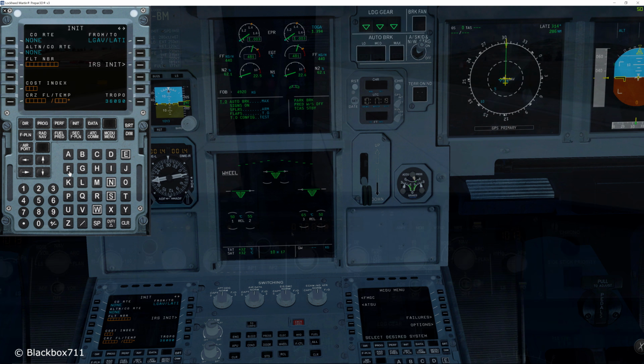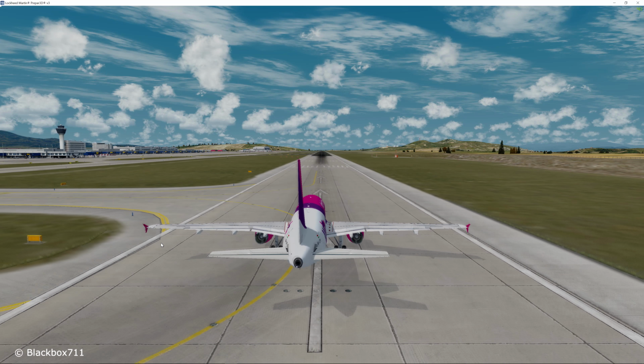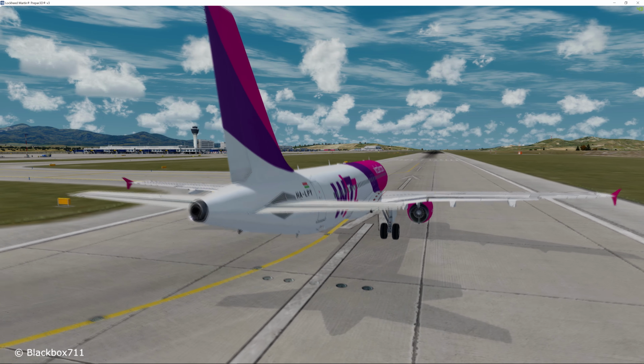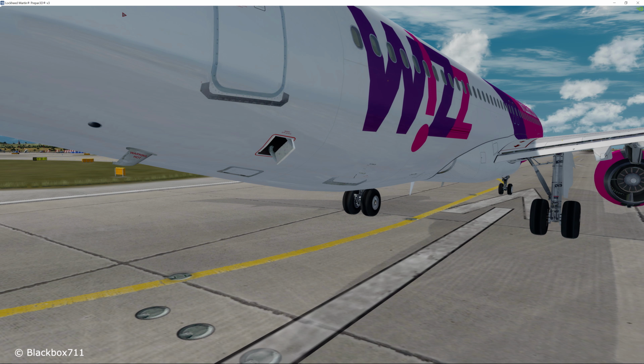And that is because now the FMS has a destination airfield and hence the destination airfield elevation. And so it can calculate the proper pressure that it needs to set once you land at that destination airport. Now the nice thing about the pressurization control in the A320X is that it is fully automatic. So you've inserted a departure airport, a destination airport, the flight level you're going to fly at, and so the FMS and the pressurization computer can now calculate a proper vertical flight profile.